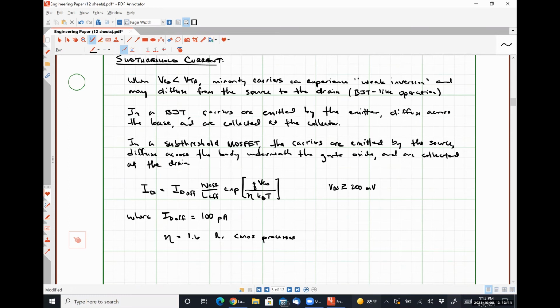And then in truth, there should have been a non-ideality factor there for PN junctions. For whatever reason, it's typically called M, that ranges between 1 and 2, depending on what type of junction we have. Well, this ideality factor here is effectively doing the same thing. It's just slightly skewing that exponential function to either rise more slowly or more steeply, depending on how ideal or non-ideal the process is. That's all this thing is.